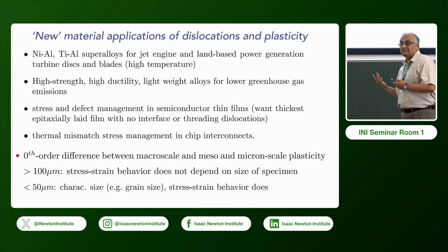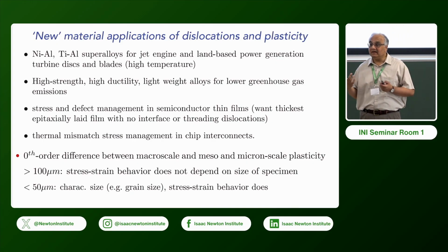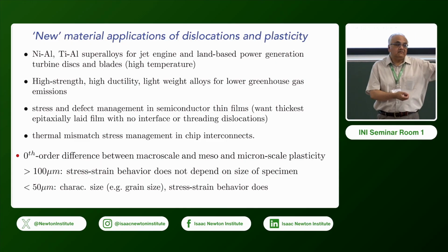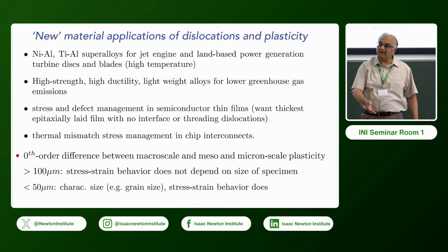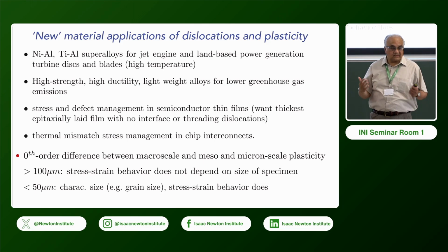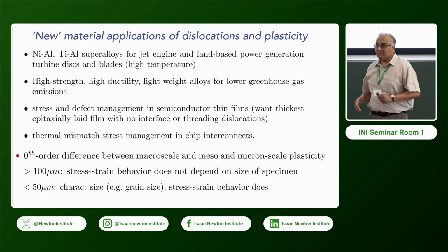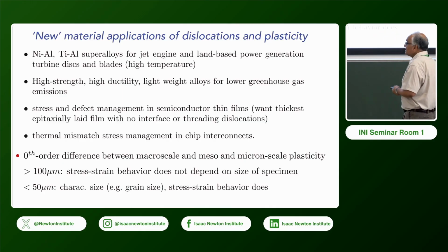And this is extremely important, to be able to say fatigue loading, because you start up this thing, put it down. These are fatigue cycles, and dislocations move, so you don't want a fatigue crack to run through a blade. This is the last thing you want to happen. And so to be able to understand these things is important. Plasticity is important for that.